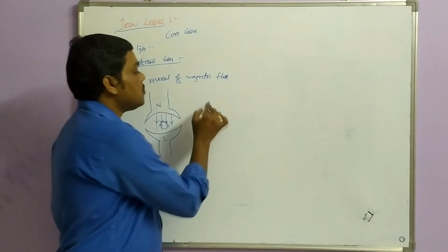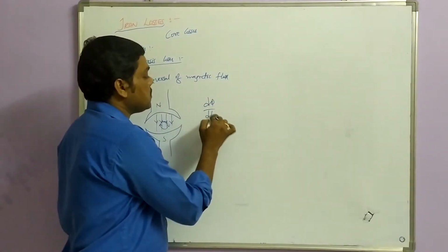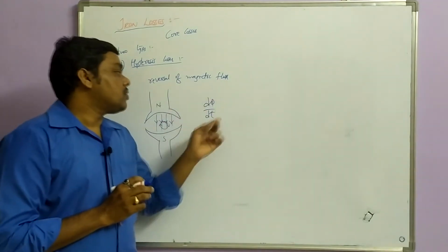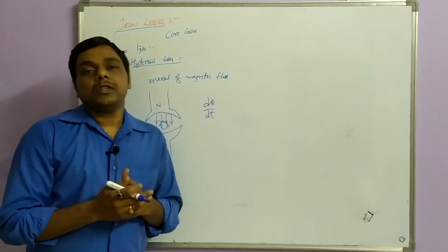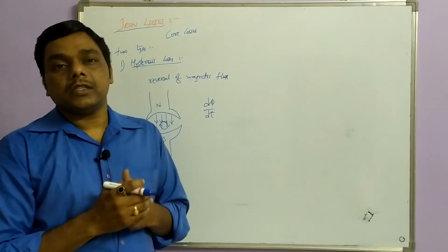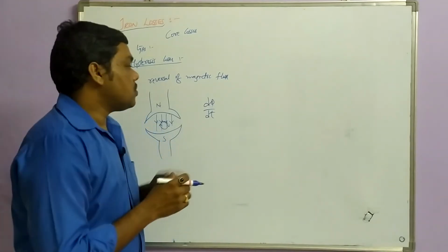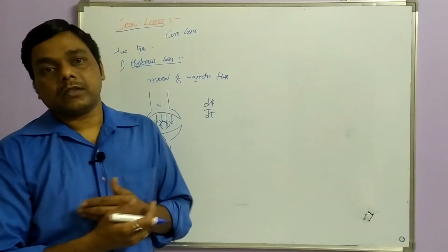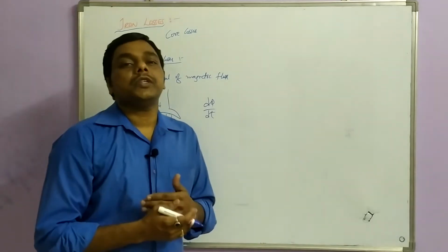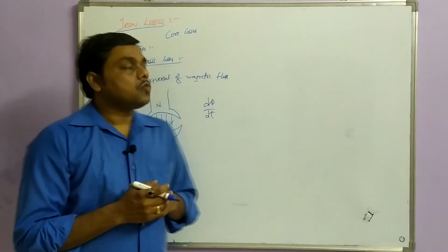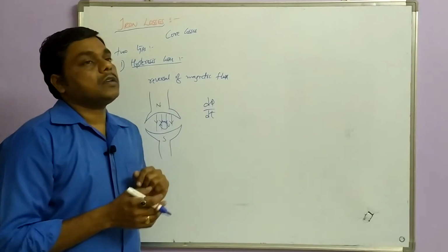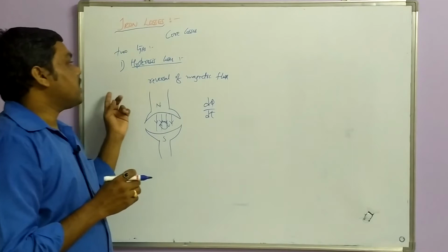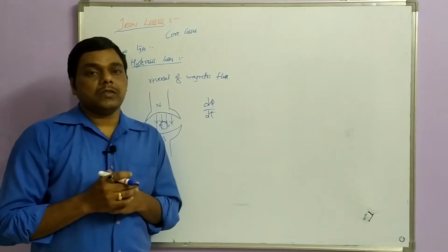If there is no rate of change of flux linkages, there is no induced EMF. Every time the flux cutting action changes, the rate of change of flux linkages changes. This causes the reversal of magnetic flux. The flux changes every time, so due to this reversal of magnetic flux, some losses will take place. They are called the hysteresis losses.